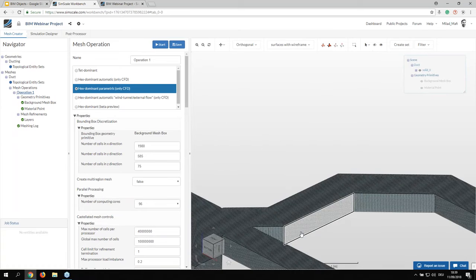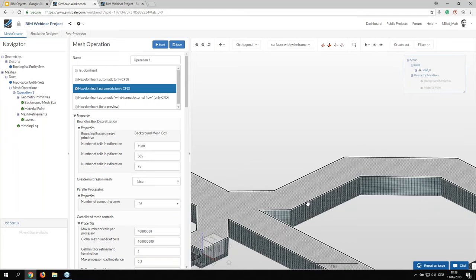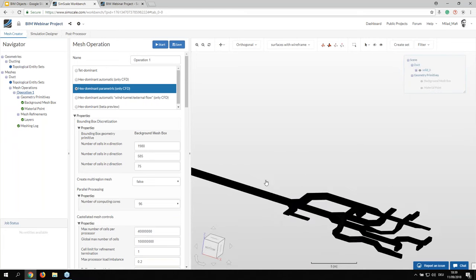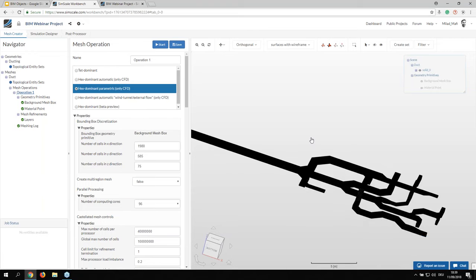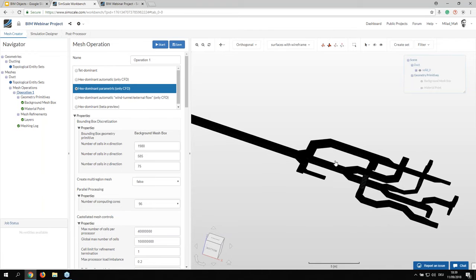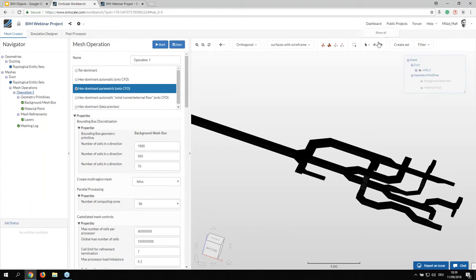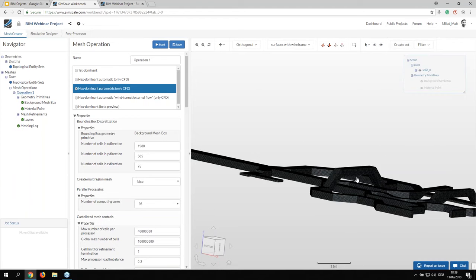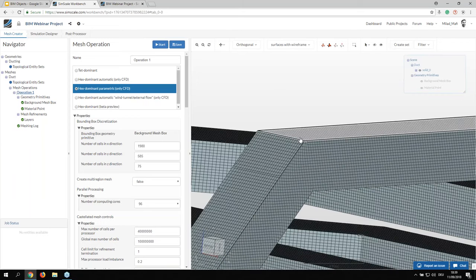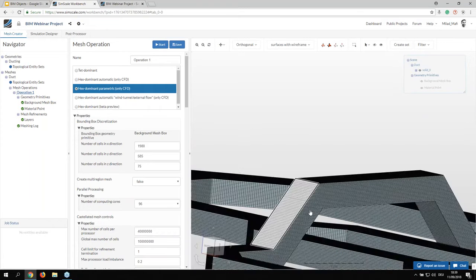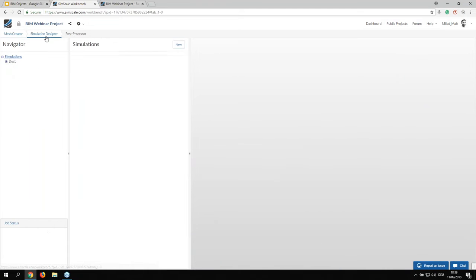And for the center of each of the cells, we are calculating velocity and pressure values. And for sure, you need to adapt the mesh fineness and make it very fine where you expect to have large gradients and large changes, and make it coarser where you don't think that we have large gradients. And we can really see how, for example, near edges, the mesh is refined automatically. And after that, you're going to set up the simulation.